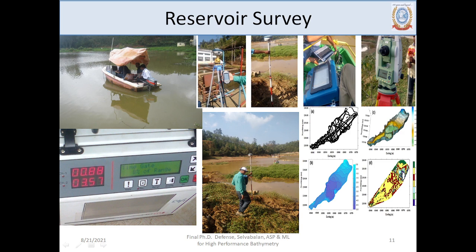There we have a ground control reference station, and you have a manual way of taking the elevation data. All put together, the dredger will give you the dredged volume based on his load of mud being removed. So all these three have to be tallied: the calculation made from the acoustic measurement, the field measurements carried out with RTK, and the load of sediment taken away by lorry loads should all match. So it matched, and hence the payment was made to the contractor without much difficulty.